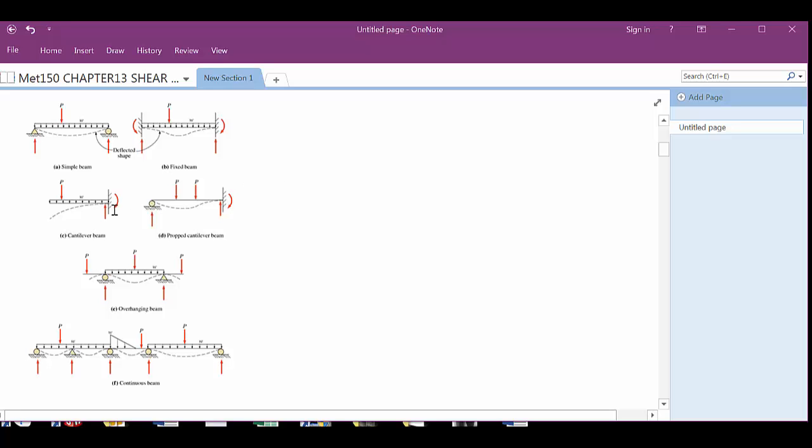Cantilever beams, and they're actually showing that cantilever beam sticking out of the wall. That could also be a situation. Do they have one? No, they really don't have one. But a cantilever beam could also be like this, where you have your beam going across here, and you might have a pin reaction here, and then you could even have a roller reaction here. It's cantilevered on both ends. Okay, so that can happen, right? Nothing wrong with that. So that's another.